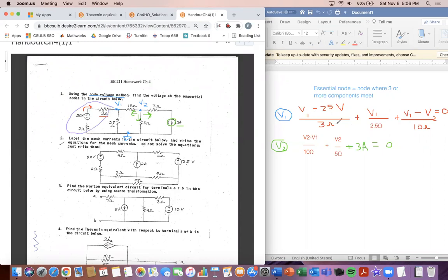And so you need to add here a plus 2 ohms, because it's in the same branch we have here. And so the 3 plus 2, that's what you need. So you are using that component because the current does have to go through that resistor as well for this branch. And so now that we've got our equations all made, we're going to have to put our V1s together, our V2s together, and then form a matrix to solve.